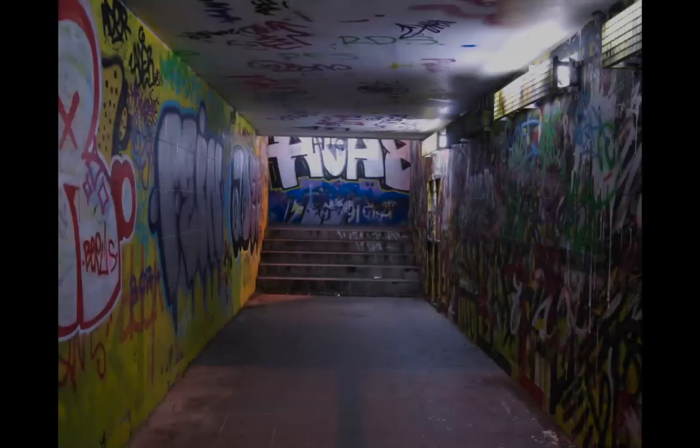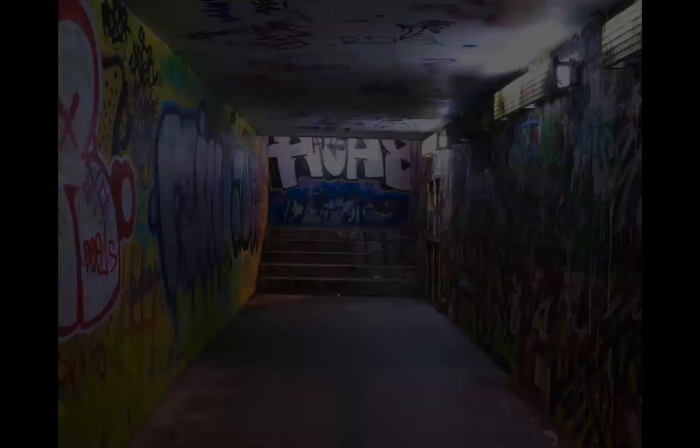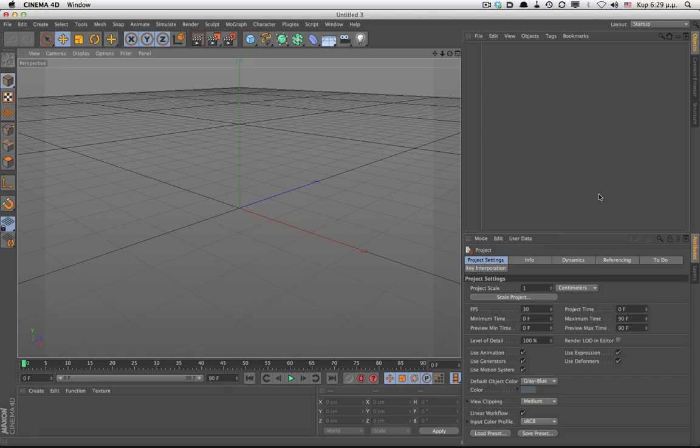Most of the environment is just one picture, and the rest are some simple 3D objects. So, aside from learning how to camera match our photograph, we are also going to find how useful the camera morph tool can be. In just a few steps, we can set up an animation that is easily adjustable and quick to set up. Camera mapping works by projecting a photograph to some simple 3D geometry. We use really simple geometry, but through the texture work mapped on the geometry, we can trick the eye that there is a lot of complicated work being done in the background.